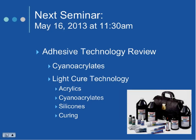And actually I'm thinking about another client. They had issues trying to accelerate a silicone-based material's cure, even if they're at a certain number of hours, they're trying to accelerate that. It's really case by case. It depends on the adhesive too. In the medical line, we have two pure UV visible curing silicones. That's the only thing that will cure them. Light has to get to the bottom line. We have a third one that has a secondary relative humidity moisture vulcanizing cure. So you could expose it to higher relative humidity and bump it up a little bit.